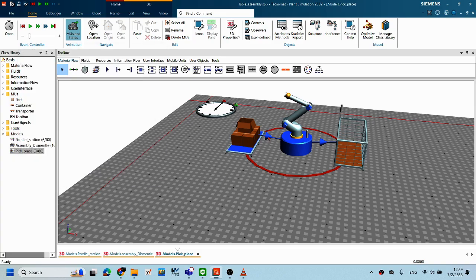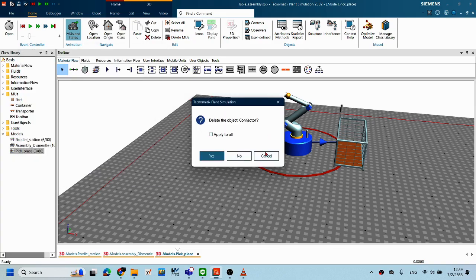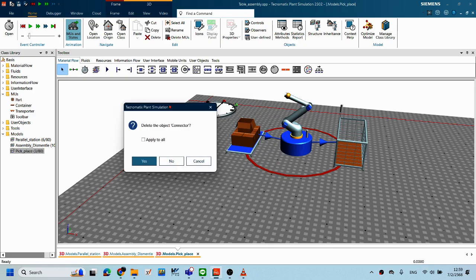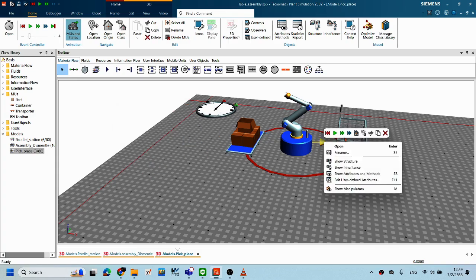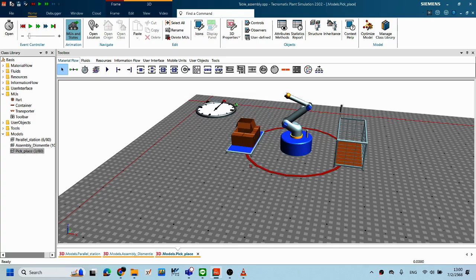You must delete it again, because the connector is for the previous posture, the old connector, and this one is for the first posture of the robot. And right now I suggest you delete the connector, right, and wire again, renew, wiring the connector again here.